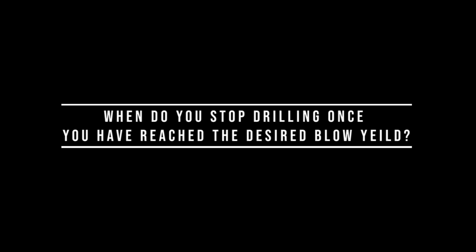Great question. So if you've met your desired blow yield, you must bear in mind that that's not necessarily what you're going to get. Often it's lower than that once you've tested it. If there's budget available, and if you're still in that good geology, there's no reason to stop, carry on. Possibly that'll increase the blow yield. If it's, for example, way above what you need, we generally go 10 meters beyond that, just to form a bit of a sump. And what that sump does is it just forms a little capture zone for any sediment or what have you that comes out of the fracture whilst they're developing the borehole.